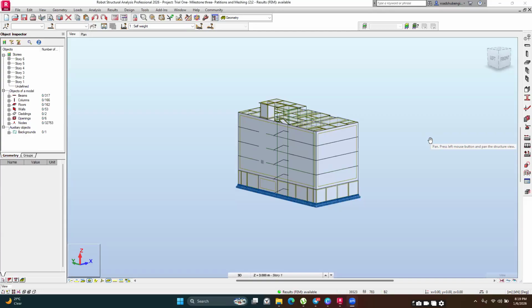So in the analysis bit, what we want to do is to determine how our members are going to behave when they are exposed to the loads. Okay. And then in the design aspect, now we are going to be designing for the results we get from the analysis. So basically in design, for given moments, you are going to use the Eurocodes to determine an appropriate area of steel required. And then from that area of steel required, when you combine the steel and the concrete, you get a stable structure, something that can be built.